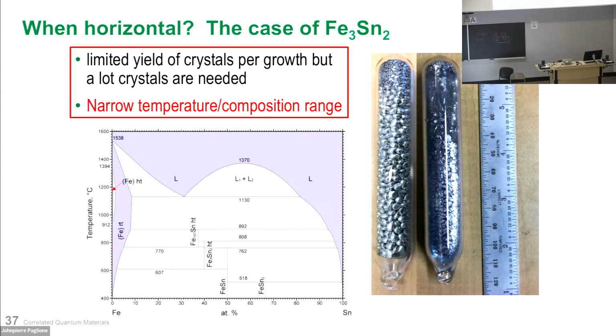So there's only like a 40-degree window where you can grow crystals using the composition over here. So you come down with the composition here, and this would be the first thing to precipitate out. But this is pretty far away from the liquidus composition you have to start.